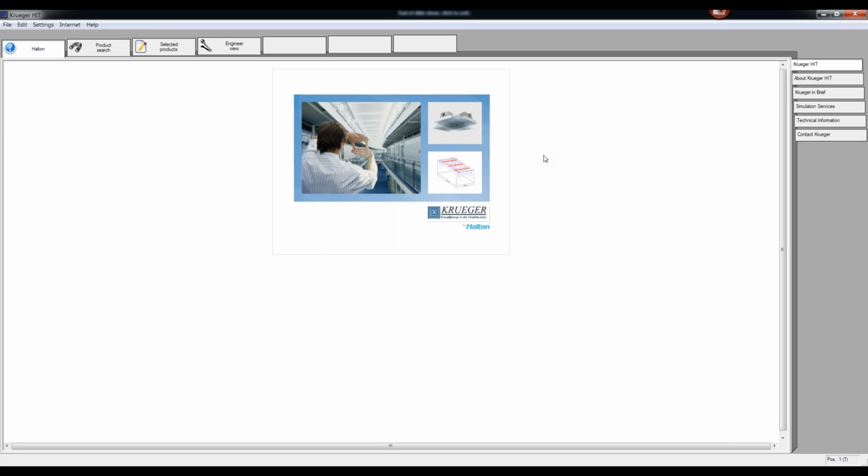units, it also gives you a visual feedback of the performance because it includes isovel patterns, and you can actually place units in a 3D virtual space and see where those isovels from that particular unit are going to go. And you can actually determine what the velocities are going to be in that space. So it just gives you all those warm and fuzzies that whatever you lay out, there's not going to be any issue of occupant comfort in that space.